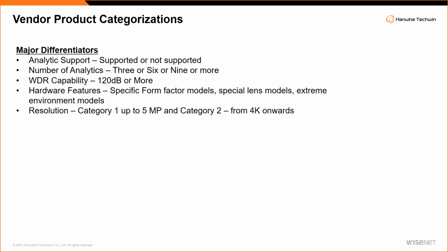Previously, WDR was also a major difference, but now it's almost diminishing. Almost every camera is WDR. Previously, some cameras were not WDR. WDR takes two pictures, so it works twice as fast, and it had a different processor and all that. So they were more expensive, but now that is diminishing. And of course, you saw multi-direction cameras. They are not a standard camera. They are like four cameras in one body, so they are also a differentiating factor.